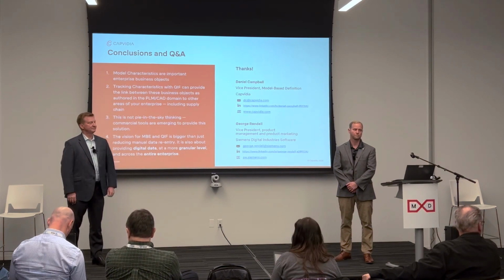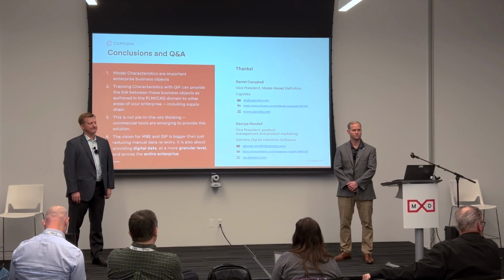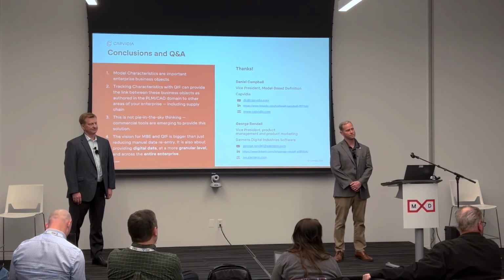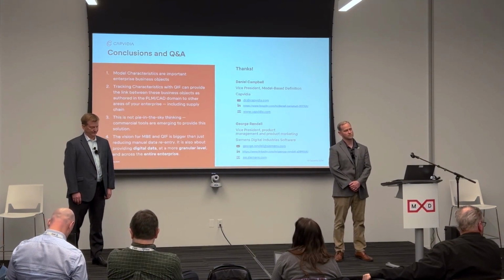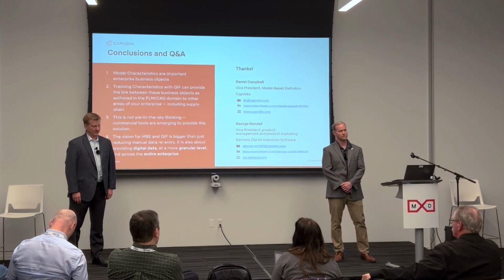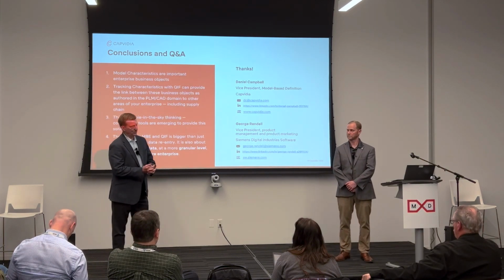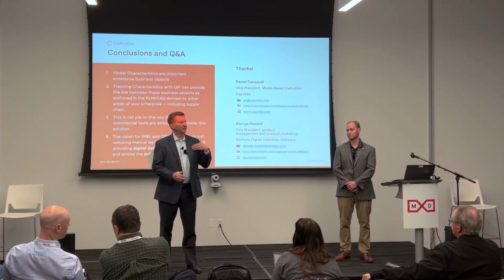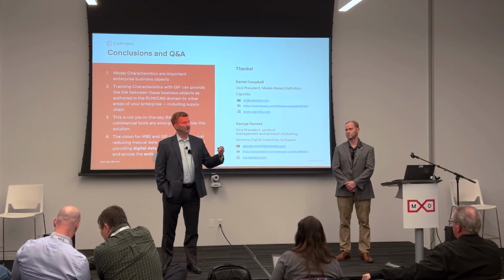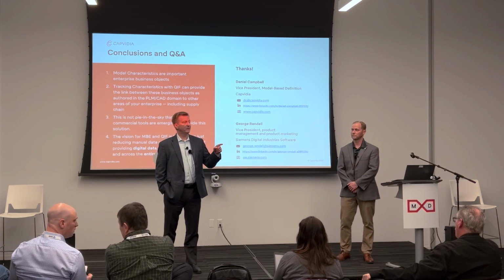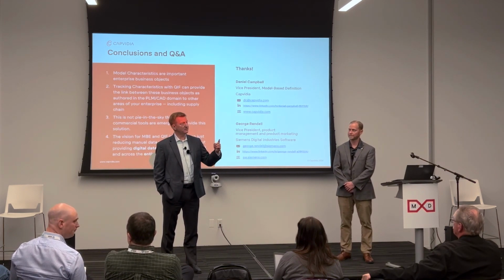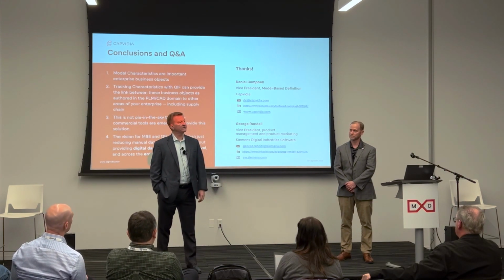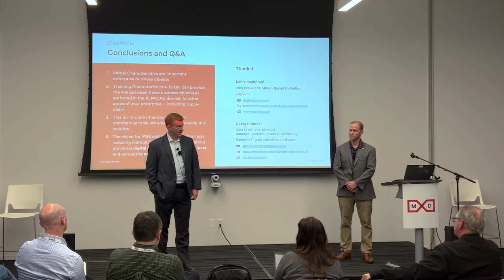Yeah. Okay. Also, I think what I heard you say is that not only did you put this in NX, the characteristics, but whenever you uploaded it to Team Center, all those characteristics got separate objects inside Team Center as well, and there's a connection between NX and Team Center. Correct. And I didn't really talk about that, but that's absolutely a requirement on our side. Okay. So Team Center will be enhanced to handle the characteristics object types, and the PLM XML from Siemens, which is the interface mechanism with Team Center, equivalent to NX Open, will also be enhanced, and that will follow a little bit after the NX release timeline. So the answer to that is yes.